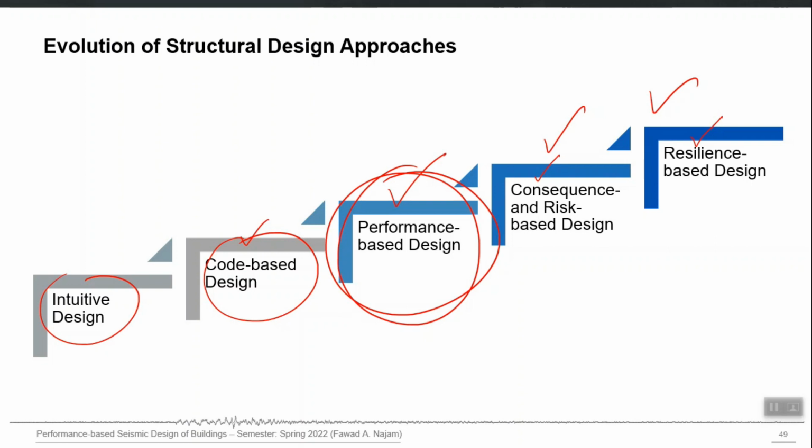So your overall design is based on seismic forces, right? That's why it is called force based design. Those forces are applied and the resulting displacements are checked at the end, right? So displacements do not have an active role in design, they do not mostly govern design, they are just checked to be lower than allowable values. So this is force based design.